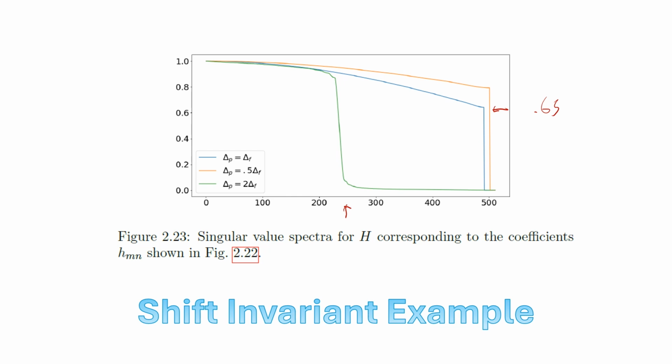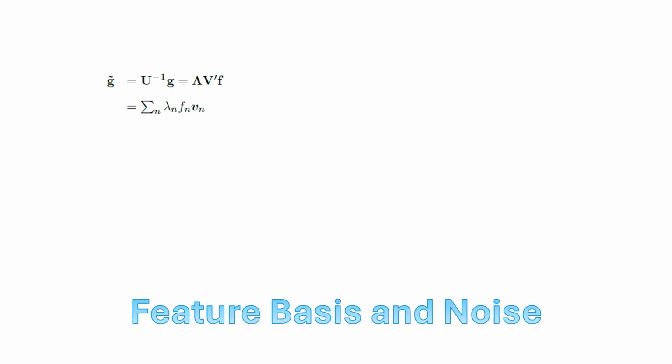We also find that the shape of the transfer function is distorted by aliasing, where you might expect, if it was a fully sampled system, even if it was sampled at the right period, to have a sort of sinc transfer function. When we undersample the data by sampling only at the sampling pitch equal to the width of the sampling function, we get artifacts that distort the overall reconstruction.